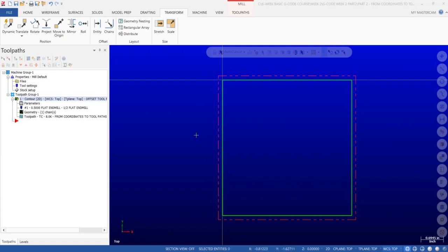So once we cut away that excess, we need to be able to find the origin by touching off on the top leg and the left leg to find the origin of that part again. So always make sure that you put the origin on the finished part, not on the intersection of the excess material. Okay, I hope that makes sense.